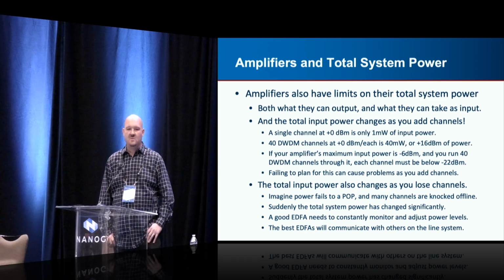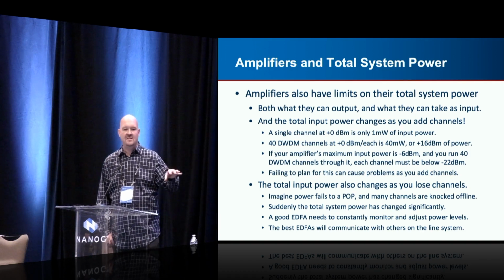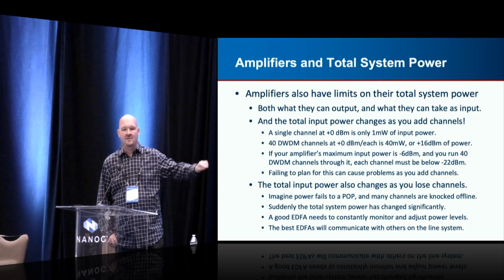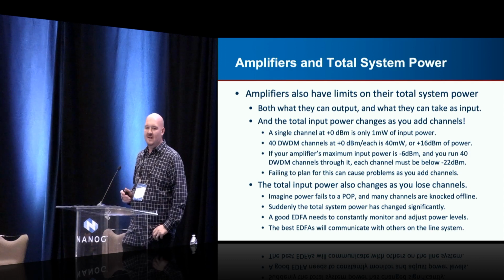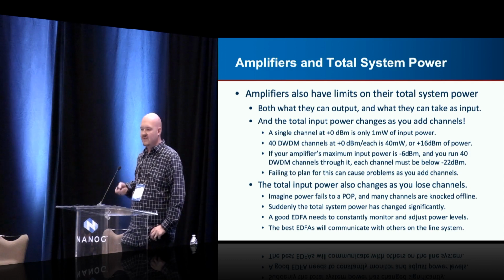And the best EDFAs will actually communicate. They'll have an OSC, a control channel that talks to the other EDFAs further down the line to tell each other what they're seeing about the line conditions and to work together to affect the signal.